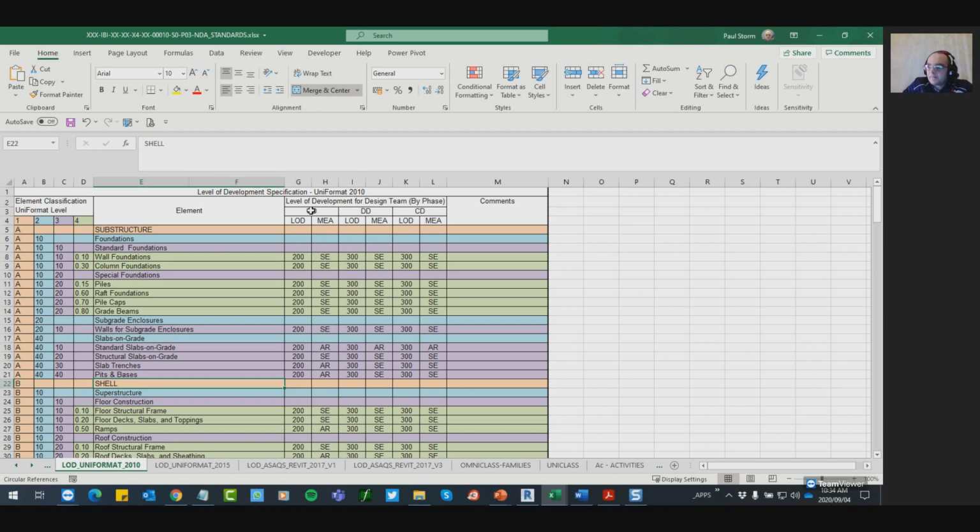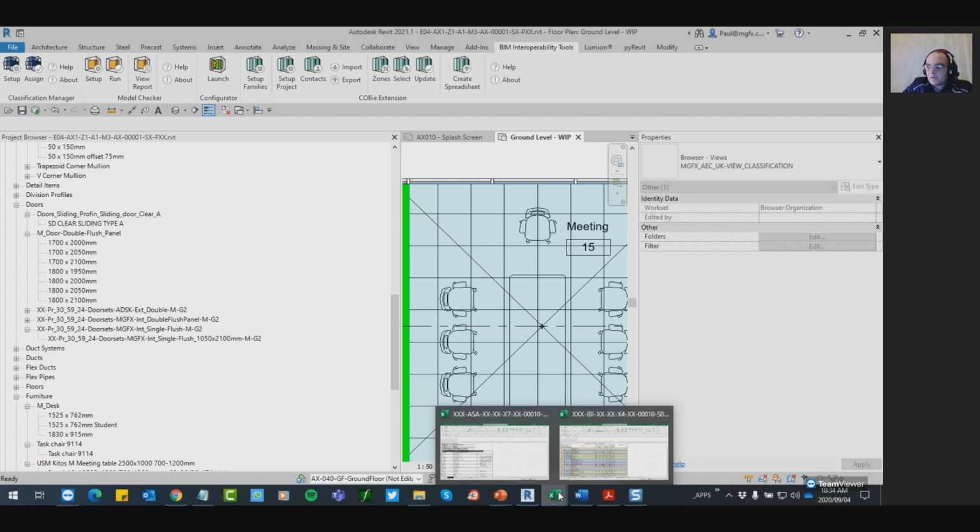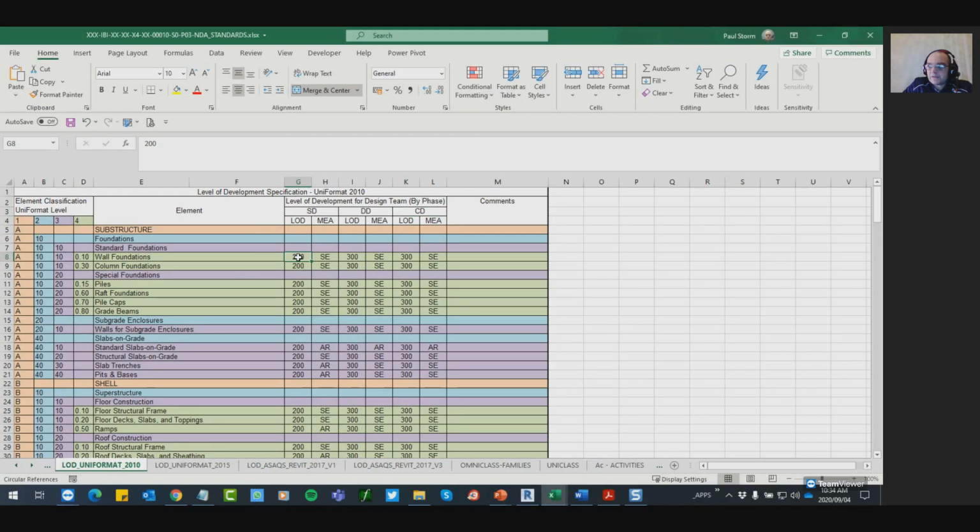And then under the conceptual design, detailed design, the construction detailing, so typical 3 phases of our models, we would see that the BIM manager is responsible for setting up the BIM execution plan will state the level of development. So when the family refers to a G2 in a name like that, then it would correspond to a level of development of, say, 200.